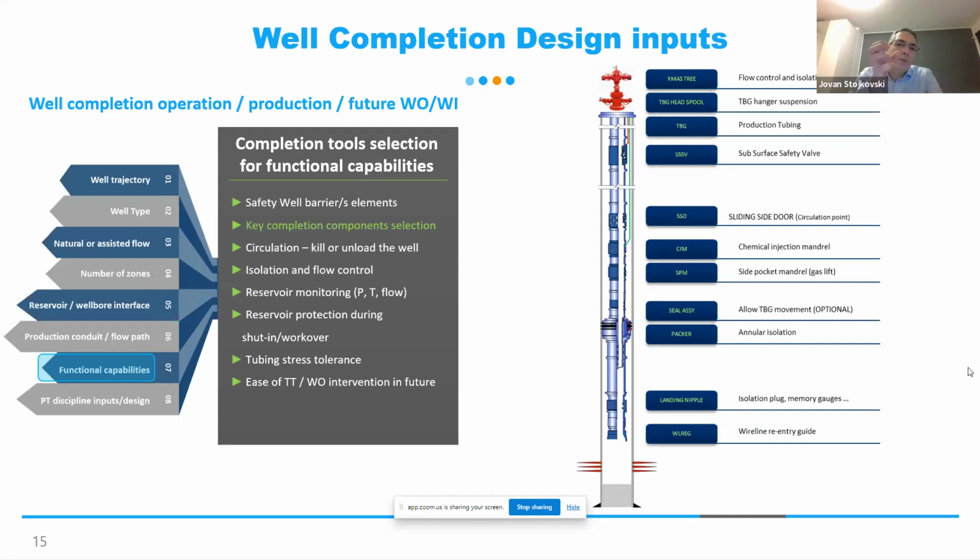A safety feature which you put in the tubing in case something happens, some emergency shutdown: you press one button and you can close the well downhole. In some countries, this is defined so that they require it in every naturally flowing well, regardless of how much production you obtain from the well.